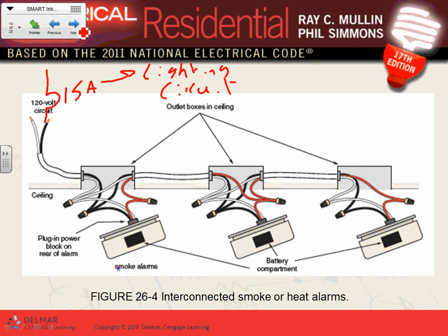So Kerry, my friend, when you did your lights, go grab a lighting circuit now for Chad, and you're going to put a smoke detector in every bedroom, every living room, and every level. Every bedroom, every hallway in front of the bedrooms, and every level. We have two levels, so your partner is going to take care of level 2. You're going to take level 1.